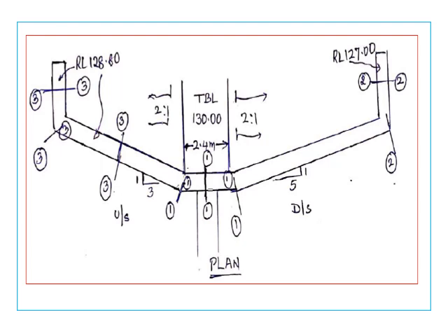Generally this downstream wing wall is given a slope of 1:5. So now when you come over to the upstream side, the water level goes to about 128.5. So that is the maximum water level. So give a freeboard of about 0.3 meters to the maximum water level, so that comes to 128.8. So any wall has to be kept at 128.8.